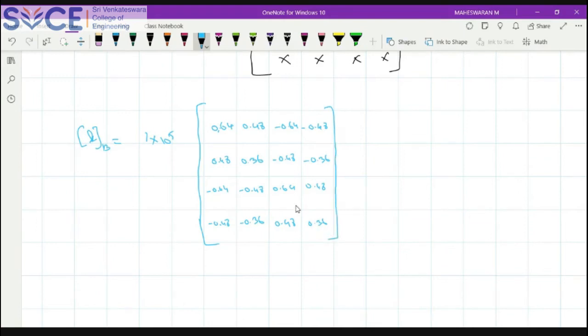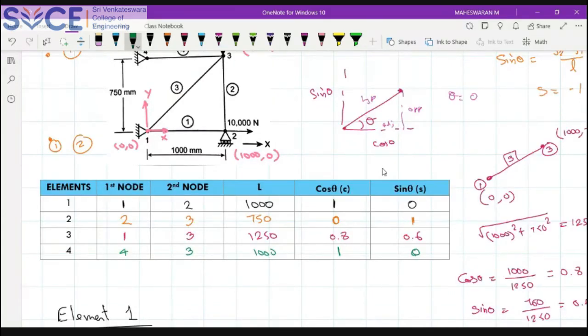As for addressing, it is connecting nodal points 1 and 3, so UX1, UY1, UX3, UY3. Similarly here, UX1, UY1, UX3, UY3. So this is my address. You can see how complicated it is. It is a time consuming process. The only thing we can do is go another way, filling only the upper triangle. Now we'll go for the next element, element 4.